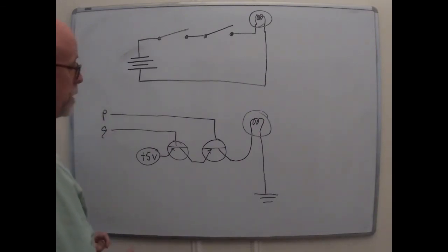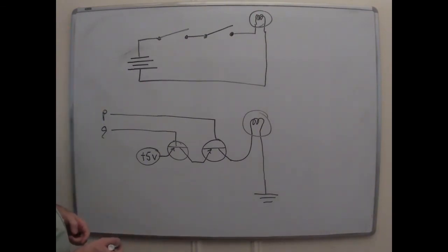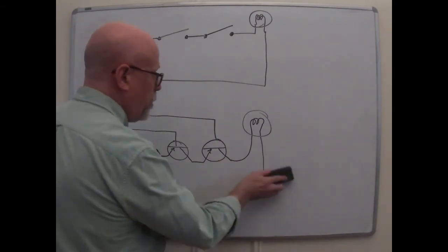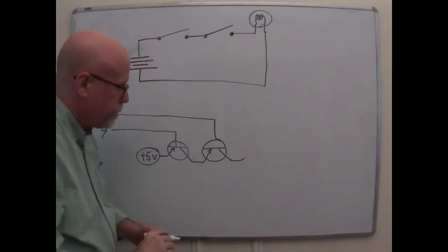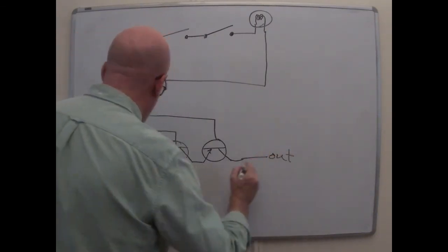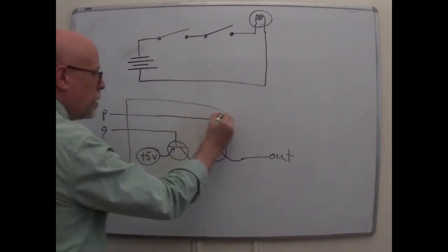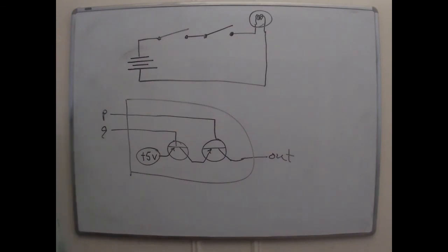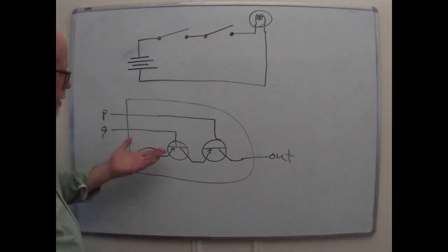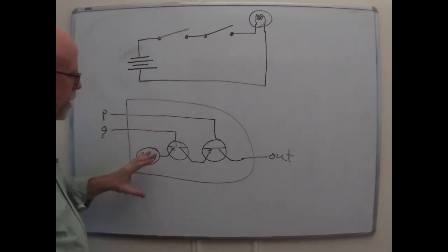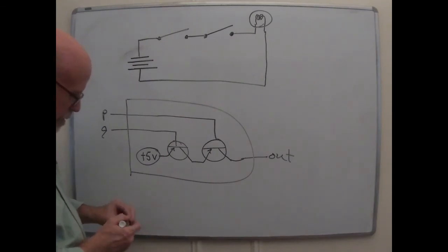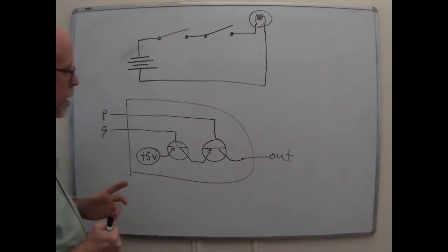And I could finally turn this into the actual guts of the logic circuit. It's not really a big deal. You don't really want to light up a light bulb. You want to supply some juice on that wire that comes out of there. So this is your output. There's your P and Q. This whole thing is what's inside one of those ANDs. Well, I'm simplifying things slightly. There's actually other elements of the circuit, some bias diodes and a few resistors, for safety's sake, that prevent the gate from damaging itself if it's hooked up wrong. But basically, that's the idea to get an AND gate.